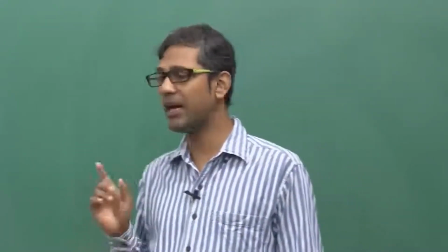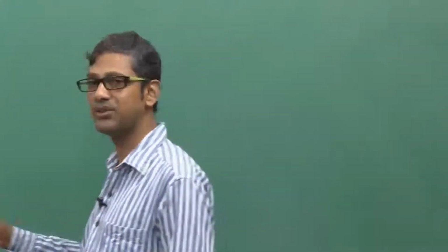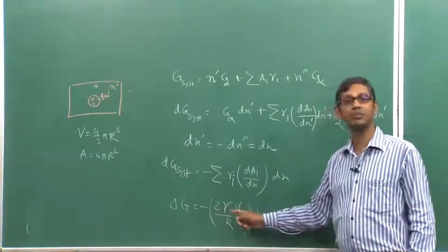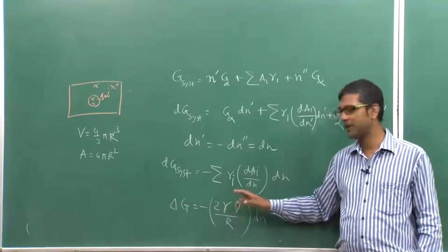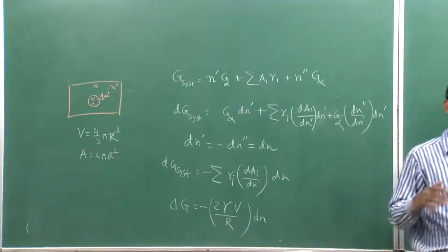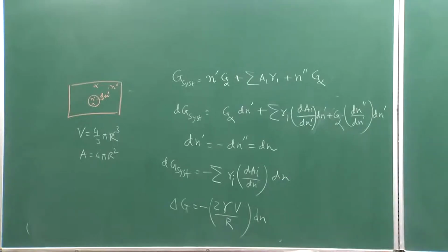Remember, one thing we have assumed here: the gamma in this equation is isotropic, which is not the case. So there will be some deviations when gamma is anisotropic. The grain boundary nature dictates whether the grain will shrink or grow.